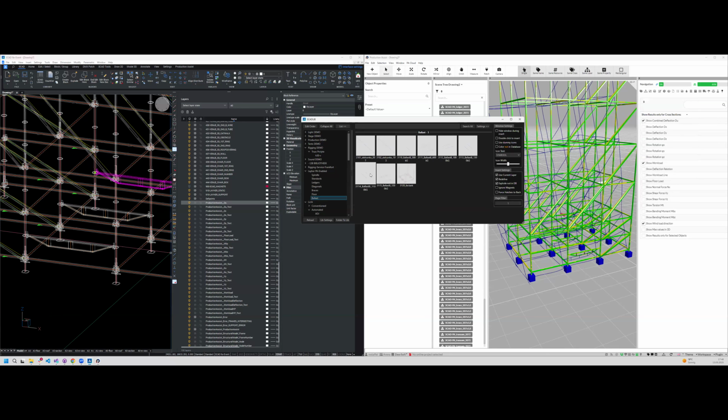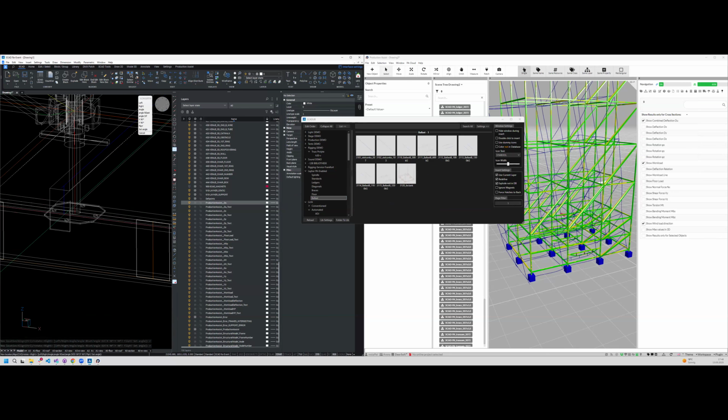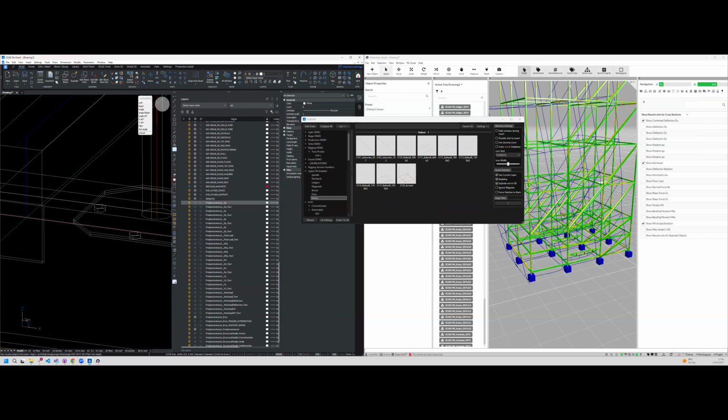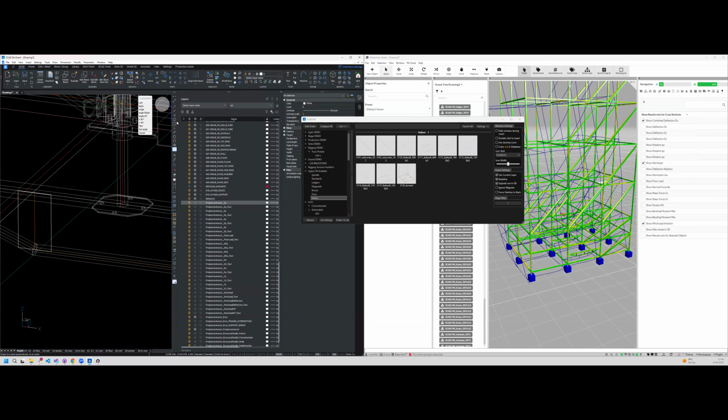So the next thing is the ballast, and for this we have some ballast steel things in here. We need again the 207 one. I need to rotate them by 90 degrees, like this. Now I need to place them on this in here. You see, it's not snapping. That's because I only have the point snap on here, so in this case you use the snap to nearest.